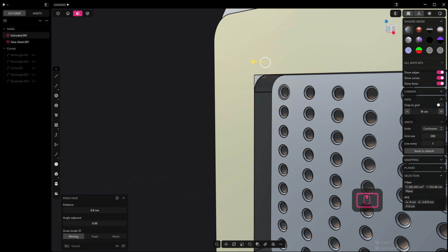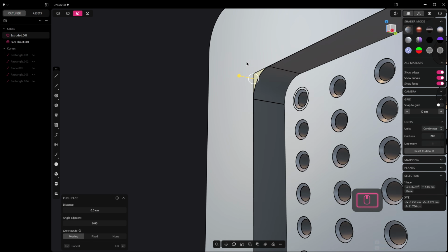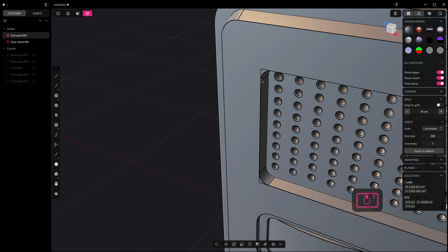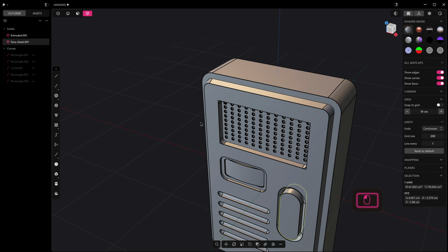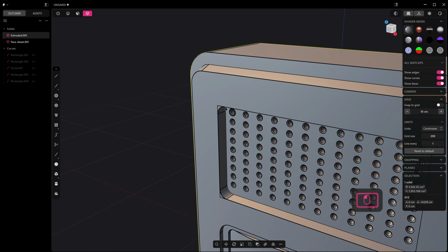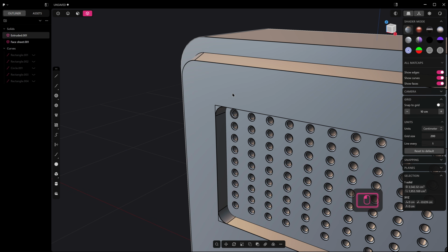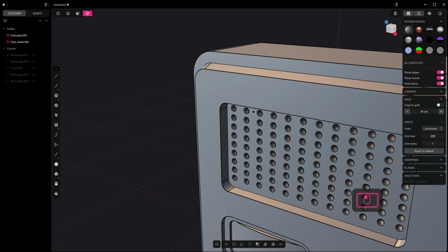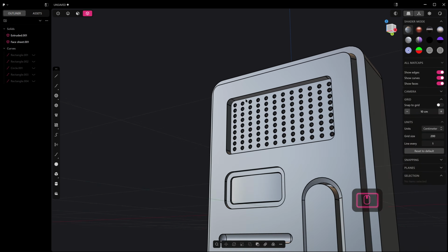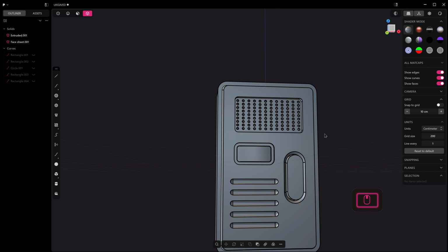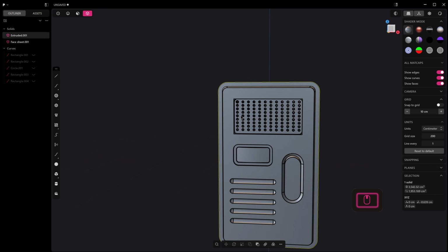Okay, I've got a funny... What's going on here? So this has some strange topology. We've got two solids. So what we can do sometimes, select our whole object and we can press F, type RED to delete any redundant topology, and that's been fixed up. Okay, so if you see weird topology, you can delete the redundant topology. So we'll just go back a step.